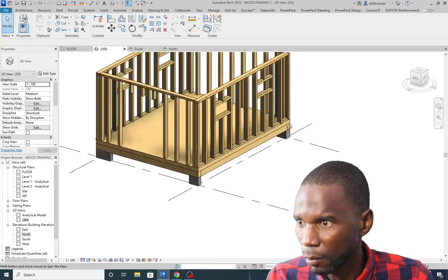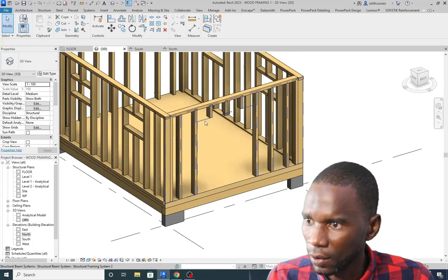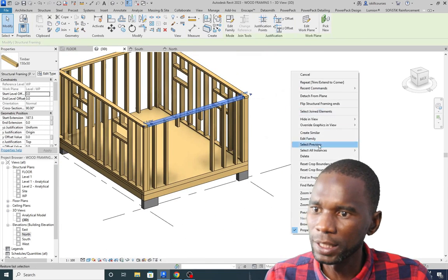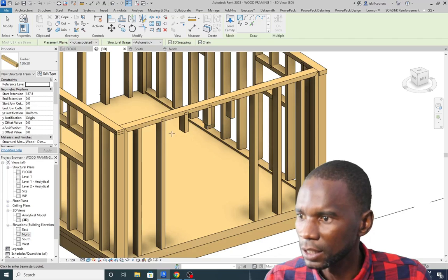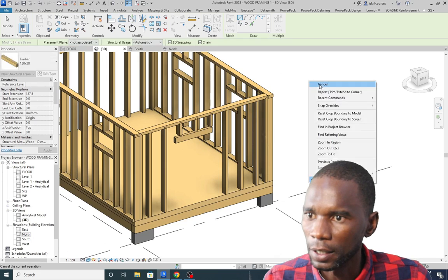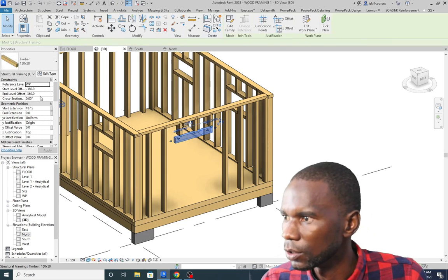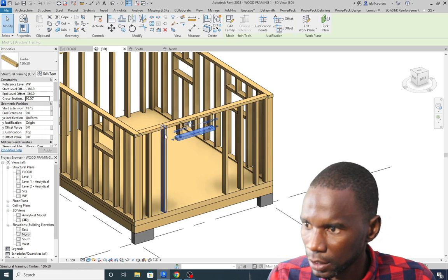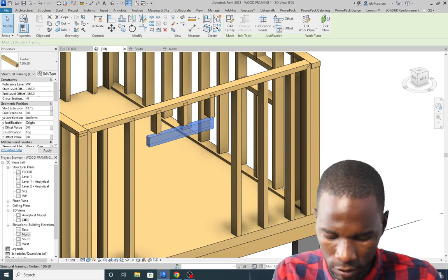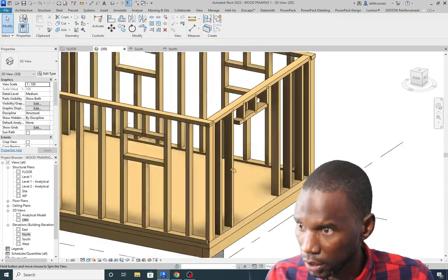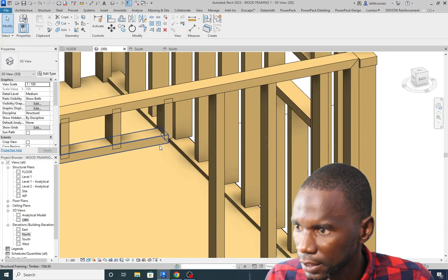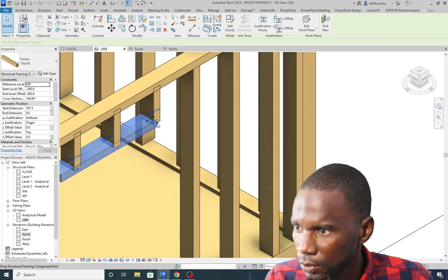You see that I have opened there. Then I can now create my beam there. Okay, so what I'll do, I'll select that beam and right click, then create similar, and I just want to have the beam there from that point up to that point. Right click, cancel, and I just need to rotate this one. Let me try 90. If I put a 0 there, okay, then if I go to -90, okay, good. So as you can see, we have it right there. Then cleaning up those intersections there, you can do that by aligning or using other methods.